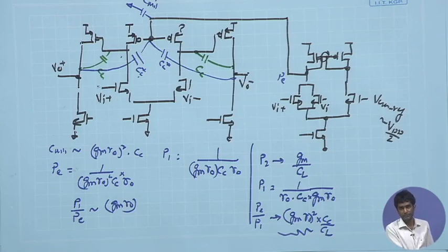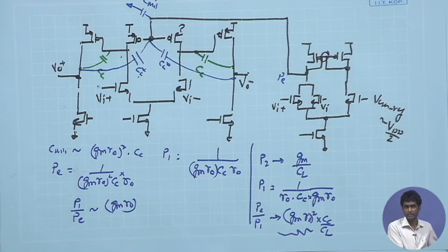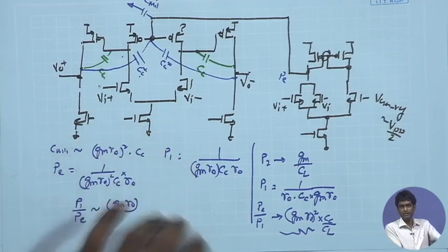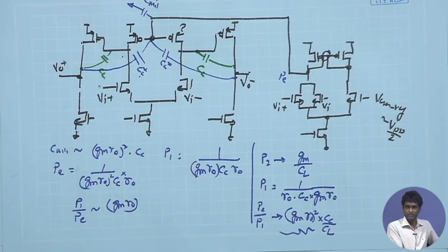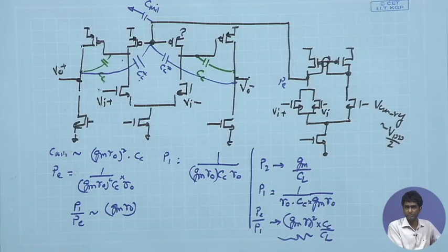Likewise, when we go for switch capacitor circuits or more complicated feedback systems, sigma delta modulators for ADCs and so on, you have similar cases. We have multiple loops where we need to take care of stability of each of those loops. So, here we are dealing with the front end amplifier only and trying to see the stability considerations in order to make the DC point stable enough, and at the same time make the differential response stable.